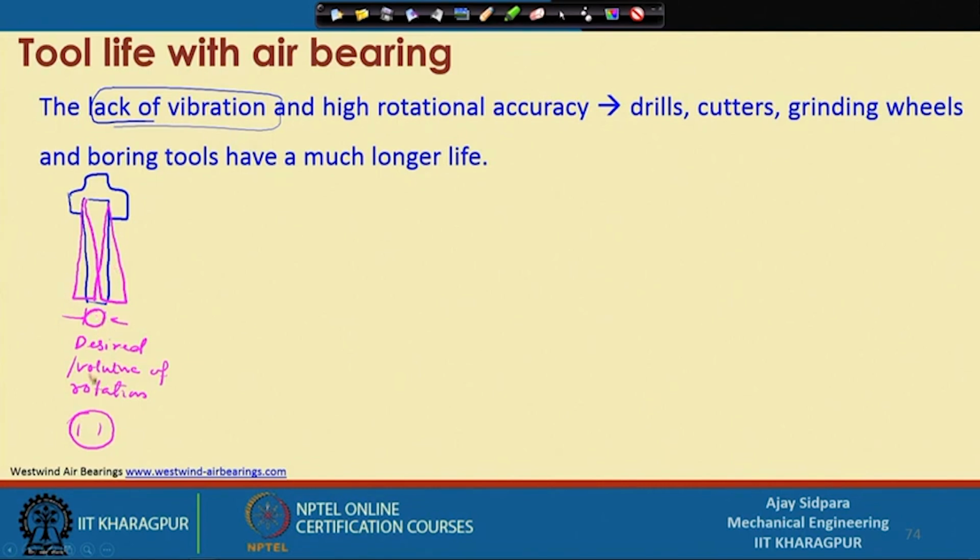But when you are getting vibration here, what is going to happen? Your actual diameter is now this much, and that is also sometimes not feasible, because what is going to happen at the end, when you are going down and down with such a vibration, your tool will be broken. It will not sustain such a one-sided force, because of this vibration or some type of runout, one of your edges will do all the work, but the remaining edge will not participate in the machining, because by that time it will come to the other side. That is the reason you are getting a non-uniform distribution of forces, and at that time your tool will be broken, and that is common for all the cases.